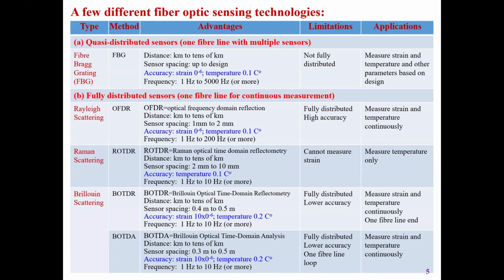But the fiber can sense, here more strain, tension or whatever, so a crack will generate. This is because of fully distributed sensing. They can identify the cracks at 1 millimeter spatial resolution. That's very good for the model test because the model test size is very small. So the accuracy is very important. So we now use this one.